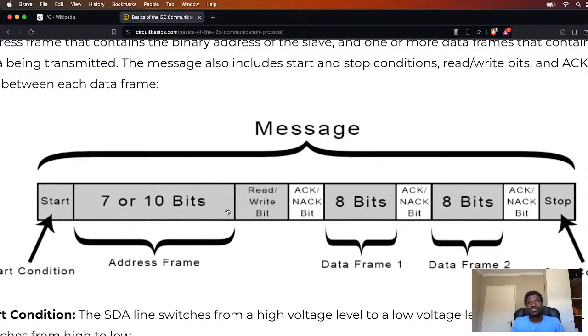So if you're going to develop an I2C driver, one of the best things you can do first of all is realize how I2C works in general, have a general understanding of what I2C is, and then after you have that and you know all the language surrounding this protocol, you can move over to the reference manual, usually for whichever microcontroller or device you're developing for.